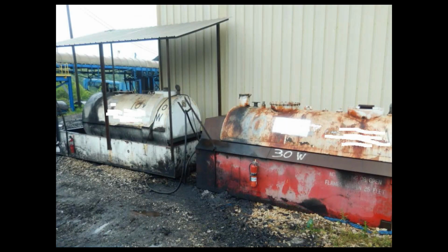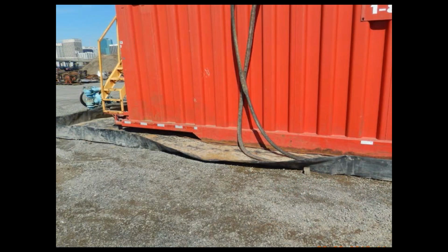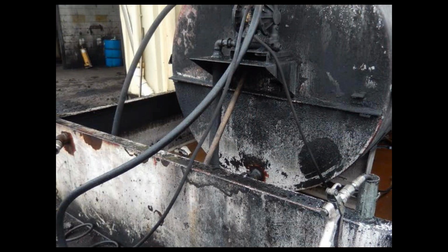Housekeeping, housekeeping, housekeeping. Just because you have a double wall tank doesn't mean that you are done. And in this case, they are not really good with their housekeeping. Frac tanks, especially on tribal lands, you may see these from oil companies. Unless they're double walled, they have to have containment if they contain oil and water mixtures. Don't use your secondary containment device as an oil storage area or trash bin. If you look at this, it's got fire issues. Obviously, they've got leakage, but you don't want to use secondary containment as your storage area.